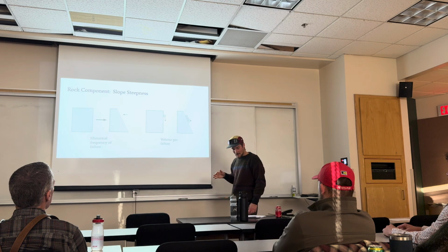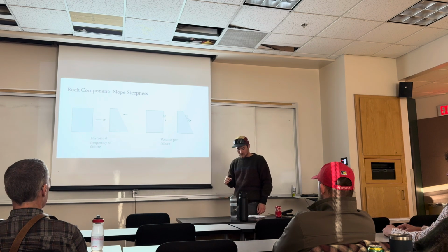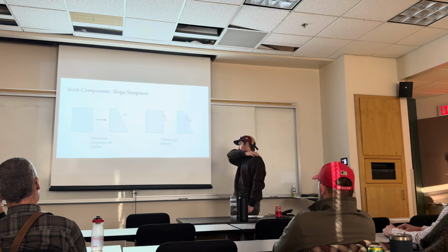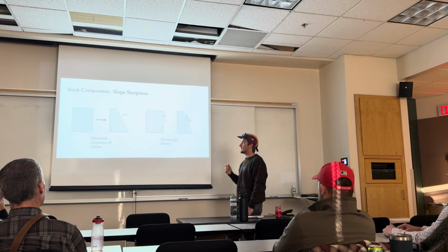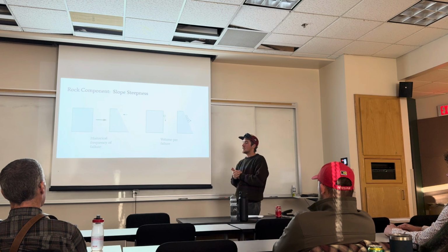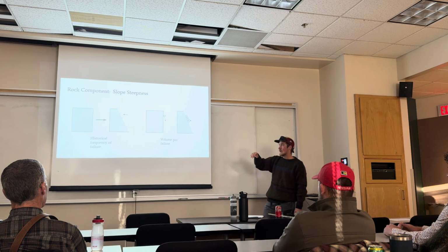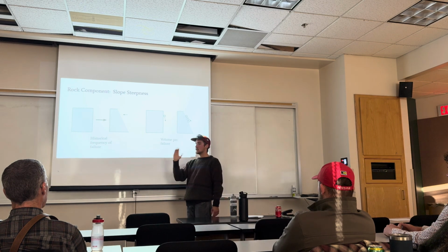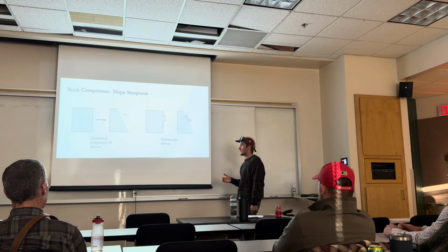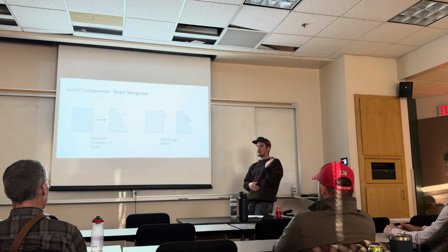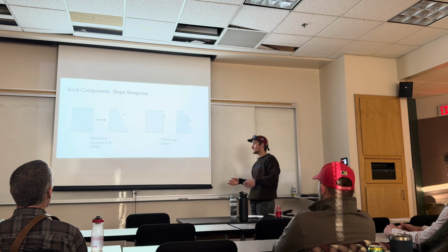And this makes it a little conceptual. So we're looking at slope steepness in relation to the ability of a head wall to transport rock to a rock glacier system. We need to understand its frequency of failure and its volume of failure. The general idea is that slopes that are steep don't fail because they are steep. If they had fallen, you would see a head wall recession back, and you'd see the evidence of failure. So if your slope is too steep, it's too strong to fail, and thus hasn't failed that often. So we're looking for a slope that's above its angle of repose, so it still has the potential to fail, but not too steep, indicating it's too strong that it hasn't failed.